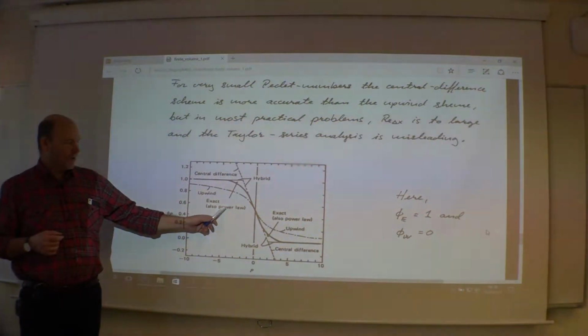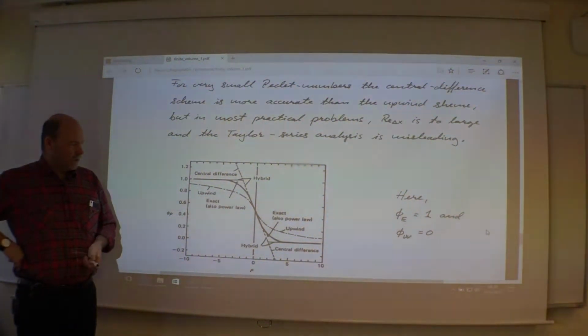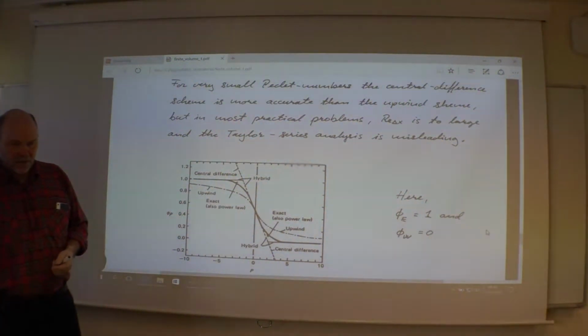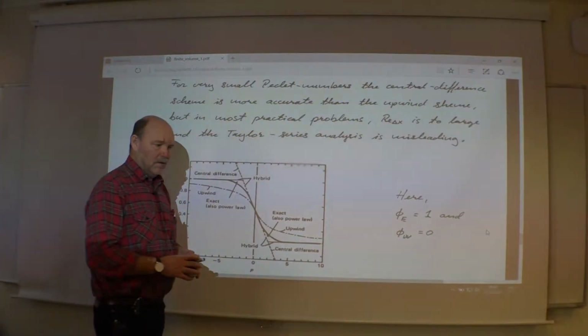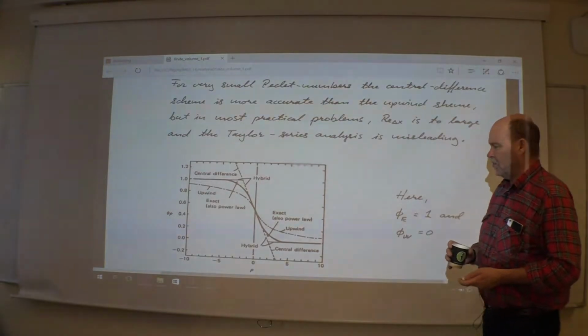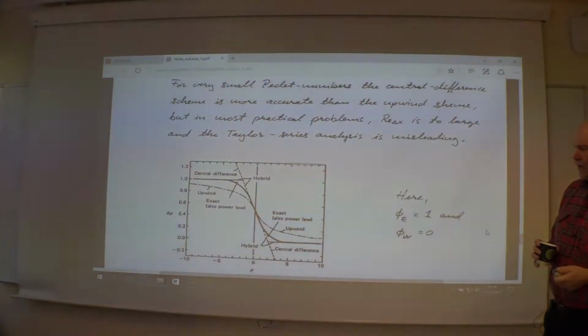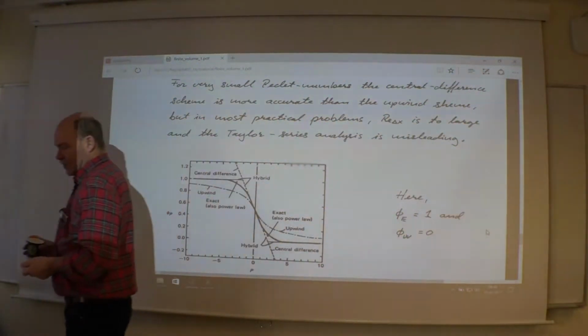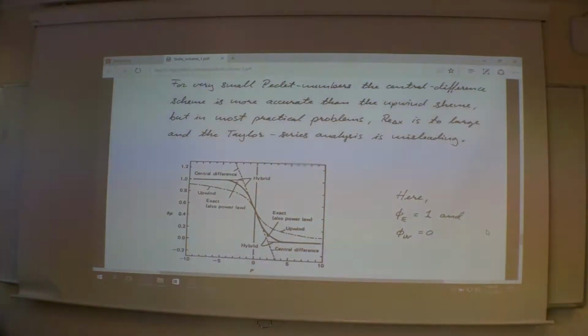Here, just by chance, it hits the exact solution directly. You have several of these more modern schemes, fourth order upwind, third order upwind schemes. You have many of them, so I won't go into details there. And of course they are in use because the problem remains: the cell Reynolds number is big. Okay, you have to do something. You can't use pure central differences. Something has to be done, clearly.